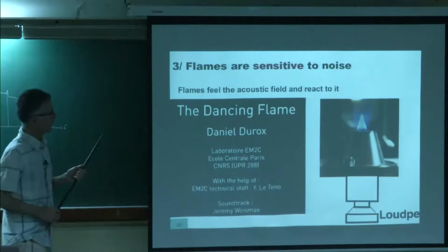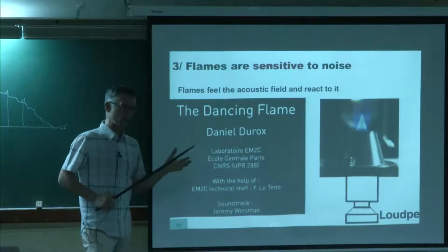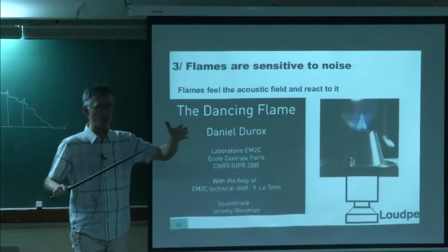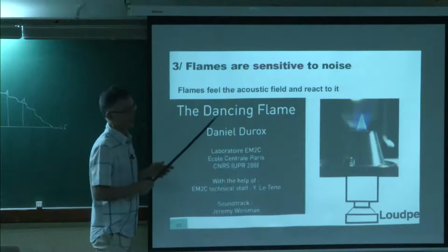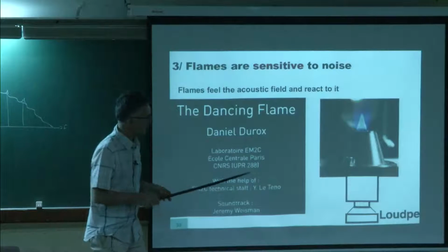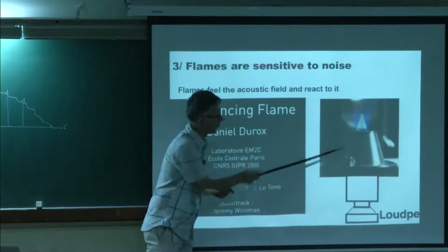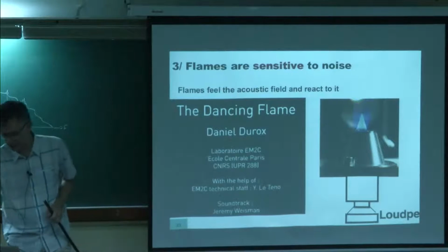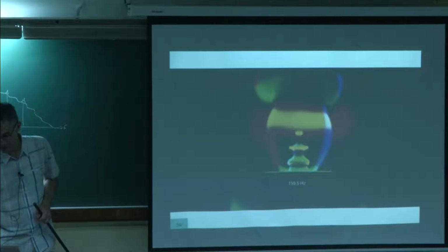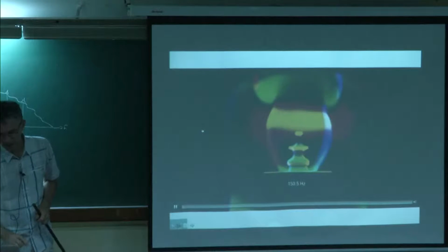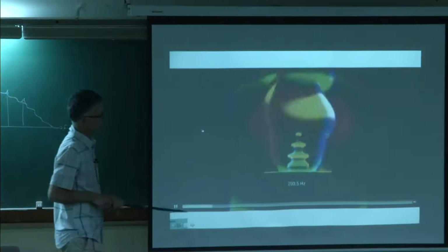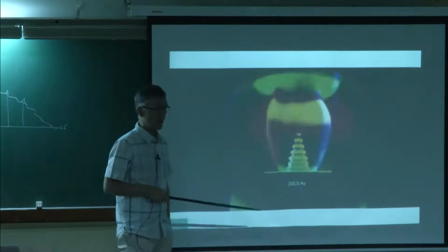So the third thing, of course, is that flames produce noise. This noise can bounce on the walls, but then flames are sensitive to noise. A way to see that is that here we use a loudspeaker to force a flame. This is an experiment in École Centrale. Probably have shown that one before. And you see here how the flame reacts. Okay. And it's actually very sensitive to noise.